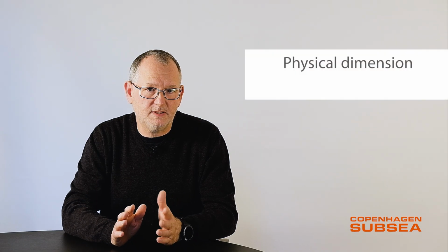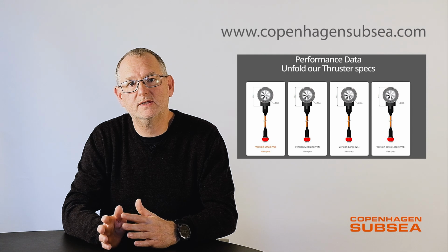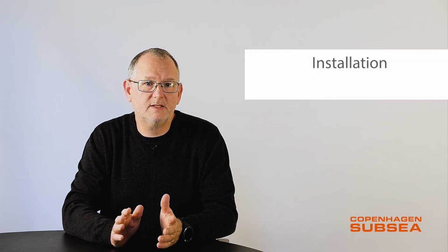The physical dimensions of the thruster is something you need to keep in mind in many cases when you design your vehicle. The physical dimensions of the thruster are listed at the Copenhagen Subsea website. You can also request a 3D file. Finally, you should consider the installation of the thruster. The thruster can be mounted as symmetrical version or asymmetrical as demonstrated earlier, but also as the compact version as you see here, which does not include the inlet or outlet ring. The compact version can be paired with a custom designed funnel or integrated into your application in various ways. And lastly, there is the option to mount it using the Copenhagen Subsea AUV mount.